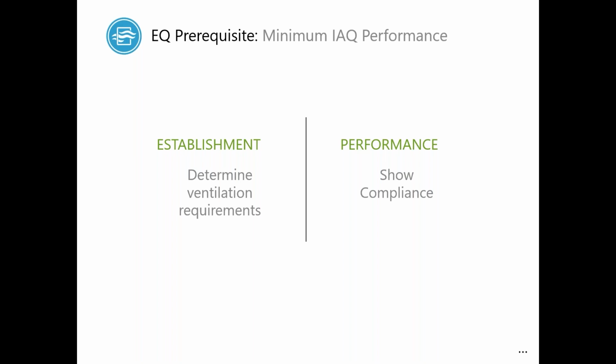Those of you who work with these air intakes all the time are very familiar with building operating systems, so ASHRAE may not be one that you need to think about so much. But for me, I really had not worked with these different types of ASHRAEs beforehand, so this is a good term to keep in mind. If you are not familiar with ASHRAE 62.1, you want to connect that in your mind with indoor air quality.